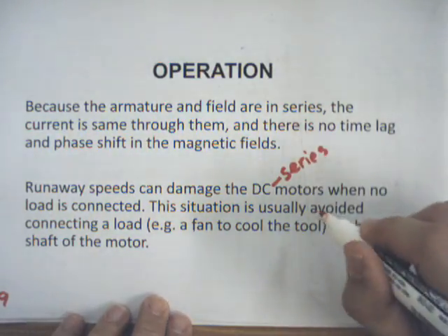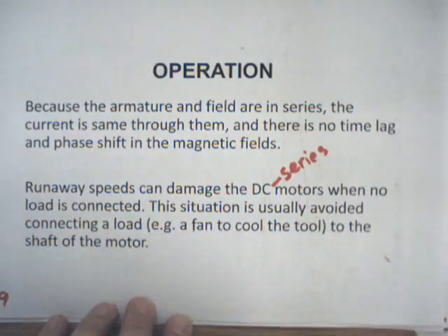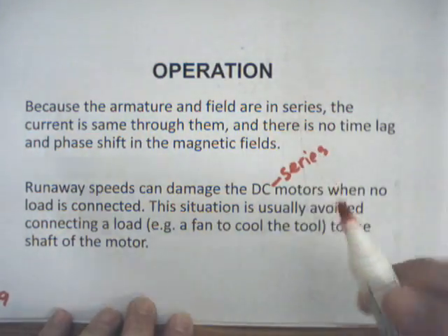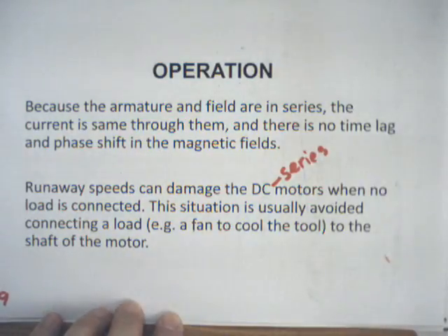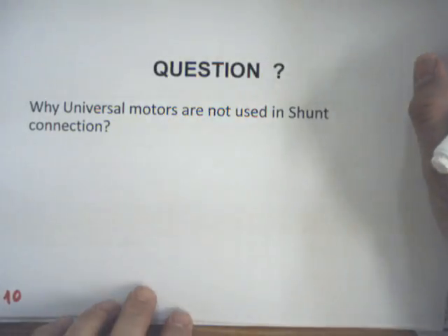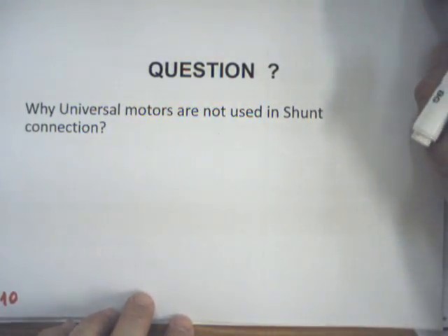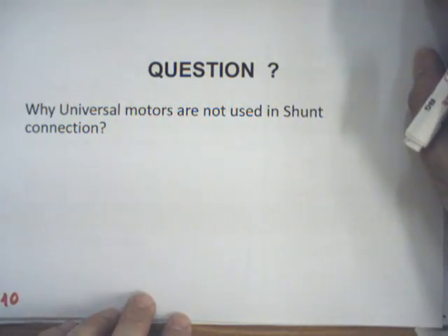So this situation is usually avoided by connecting a load. So in universal motors, always connect a load before the operation. Never operate the motor unloaded.